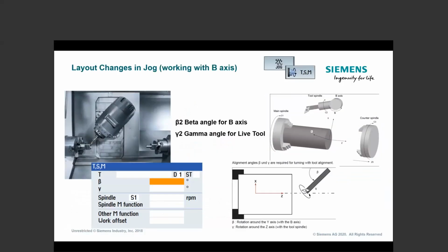Once you get your head around the axis designation, the next step would be, okay, so how do I move this machine around and get it to compensate for the tool length offset, right? So if you can visualize that B-axis head is pointing straight at 9 o'clock, I have some kind of distance from the center of that rotary out to the tooltip.